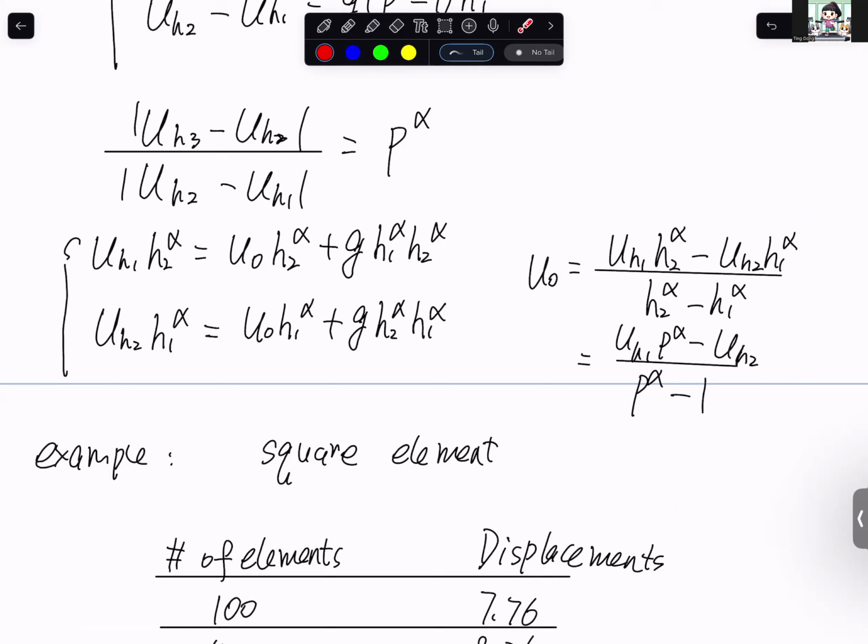Let's say in the beam chapter, if you have a uniform distributed force, it should be 4th order, but you use a cubic polynomial to model that. If it's a linearly changing distributed force, it should be 5th order, but we still use a cubic polynomial. So when it's approximation, we are always using a lower order polynomial to model something that is supposed to be higher order.